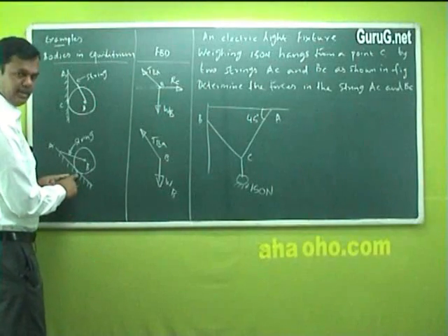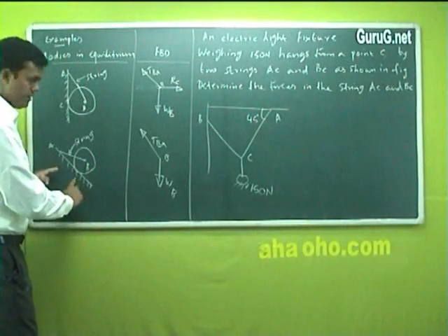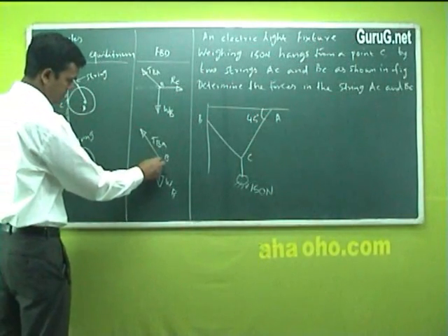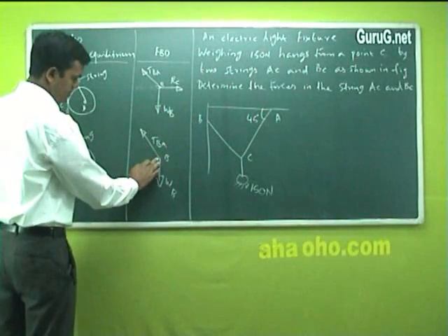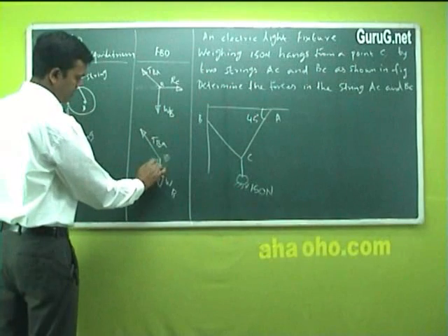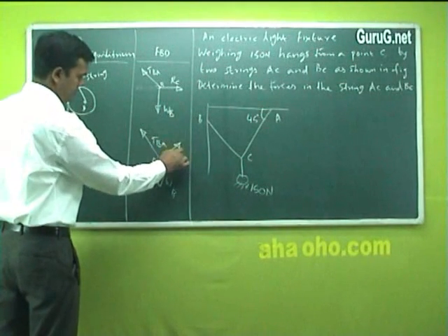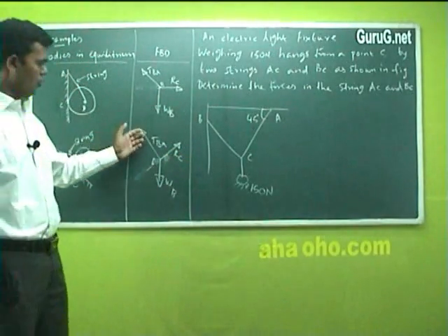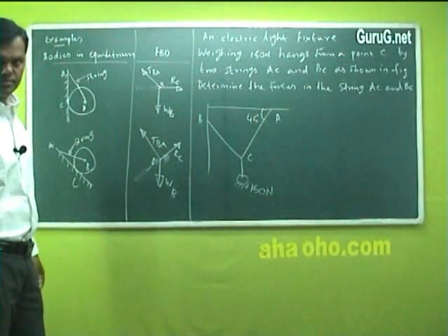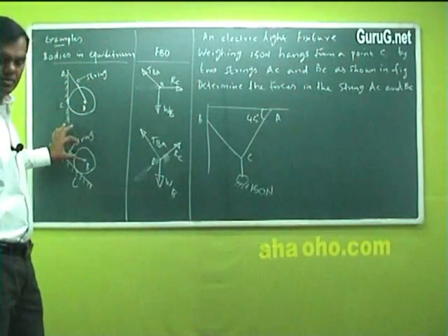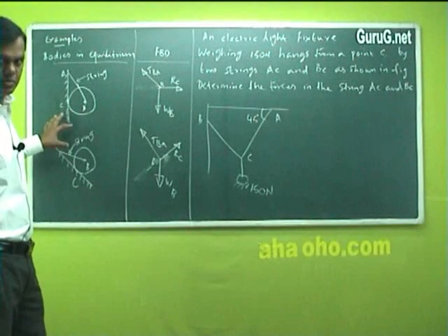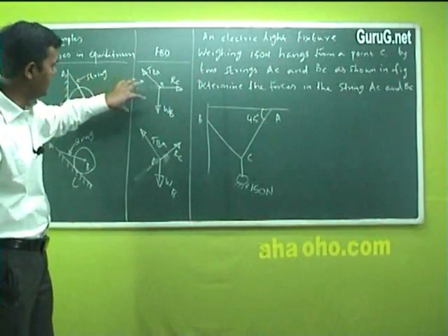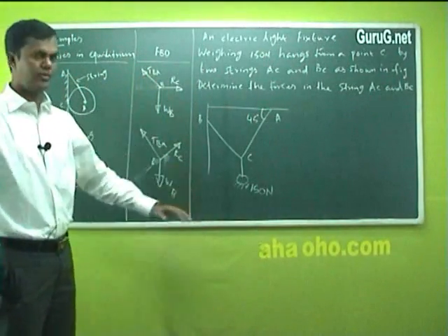And what about this? It is again a reaction, but it is in an inclined fashion. This was exactly in the horizontal direction; now it is inclined. I can show it like this, either like this or in the opposite direction. I can write this as B, and this is the reaction at point C. Now to find it, if you know one value, the other values can be found. Like this you have some 11 or 12 sketches in the reference books, which will help you clearly view a picture and immediately write a free body diagram. With this we can go for solutions.